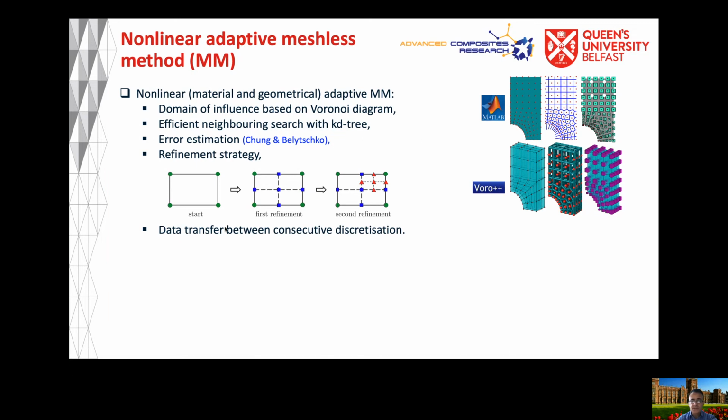Meshless methods are the same as finite element methods, but instead of mesh, we are just using nodes, and therefore it is most appropriate for problems such as large deformation, crack propagations, and fragmentation problems. As part of my research, I developed a nonlinear adaptive meshless method with both material and geometrical nonlinearities, so including both plasticity and large deformations, large strains.